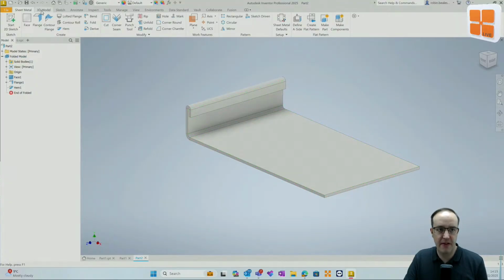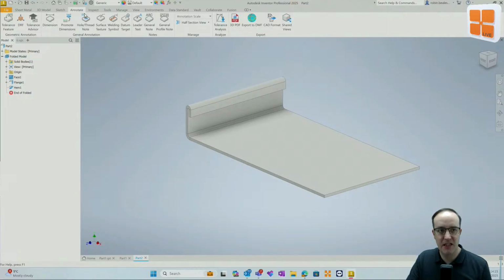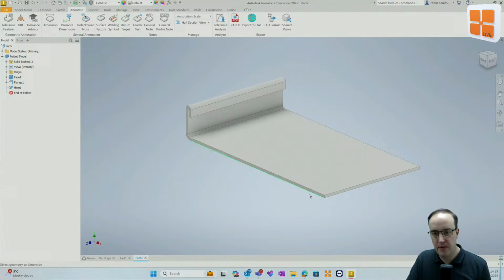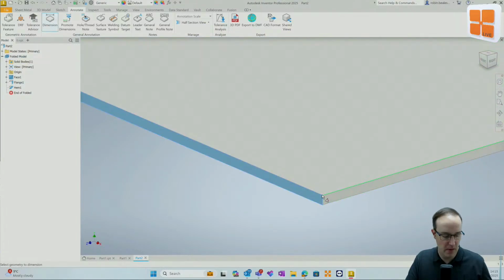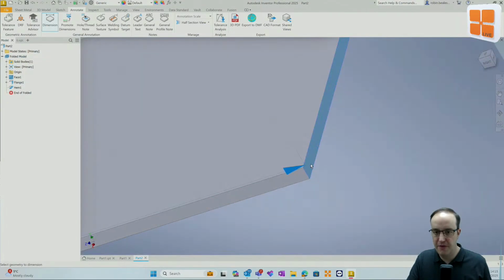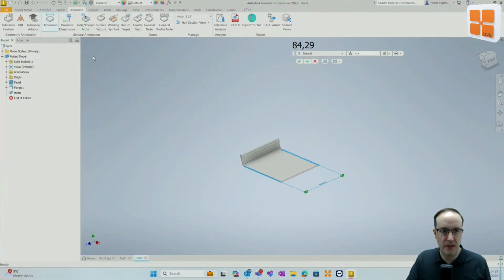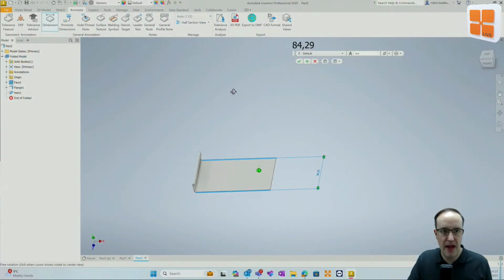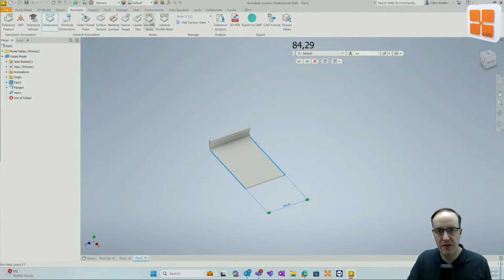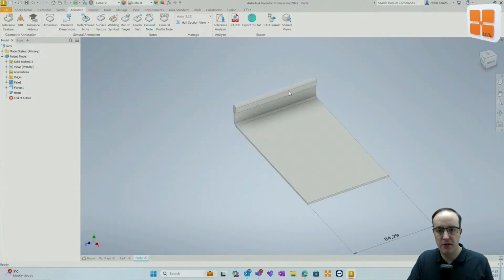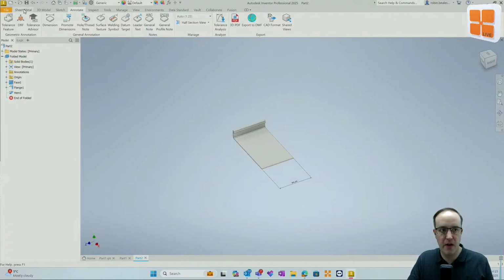Much like with the standard 3D model, I can go to annotate, and as well as adding our dimensions, choosing our standard and saying I would like to dimension from this face to this face along there, I can also choose to place notes. So I can come on and start adding individual notes and general notes to this. So I can grab a general note. What has happened to my screen there? Bizarre. And we can start adding notes to the different aspects of this file.